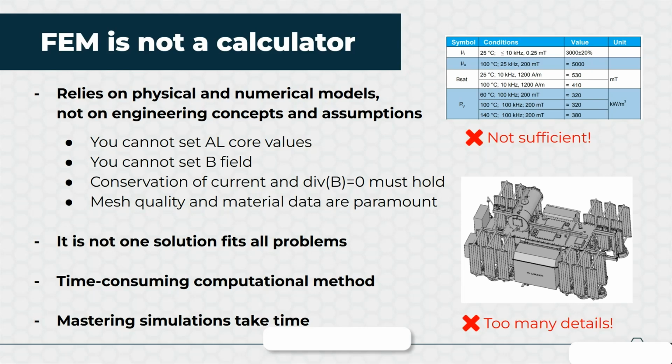Also, when you're doing FEM simulations, you have to keep in mind that mesh quality and the material data that you have are paramount. If you put garbage in, you will get garbage out, and the FEM tool that you're using will not be responsible for that. When you are doing simulations, you are responsible for the end result as much as the tools that you are using. It's also your responsibility to be sure that you stay within the limits of the numerical methods that you're using. However, from the software developer side, it's our responsibility to teach you and to provide all the details to inform you.